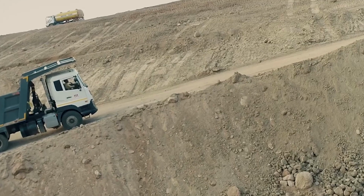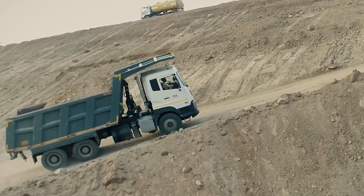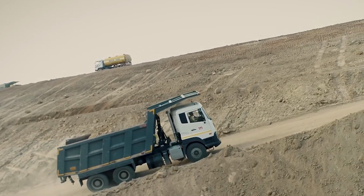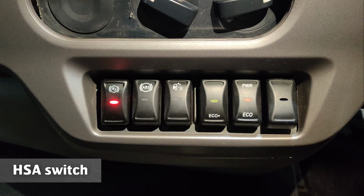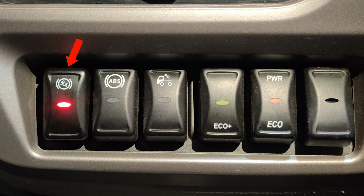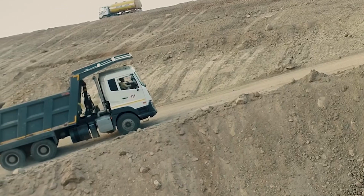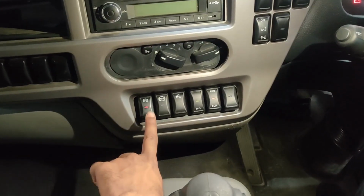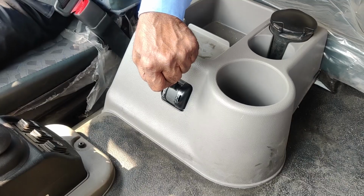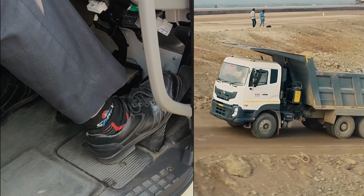Hill Start Aid, HSA. Function: to support the drive off of a vehicle, for instance on a gradient, by holding the vehicle until the transmission has developed enough torque to propel the vehicle, or after a certain time. The HSA switch is placed at the left side of the dashboard. How to operate: if the vehicle is on a gradient before launching the AMT, press the HSA switch, release the foot brake and handbrake, and move the vehicle by pressing the accelerator pedal.